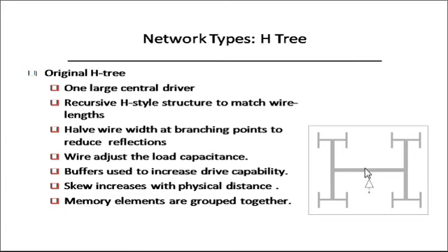Here you can see you are going to apply a clock to the center, hence you will need a large central driver. It is a recursive H-style structure to match the wire length. If you take an example, whatever may be the wire length at this edge, or at this edge, or at this edge, every wire length will be the same from the source of the clock.